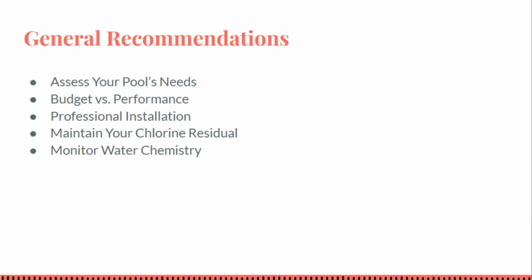Monitor water chemistry. After installation, monitor your pool's free chlorine and combined chlorine levels. You should see a drop in chlorine consumption and consistently low combined chlorine, often 0 parts per million. Adjust your chlorinator output or dosing to the new lower demand. Also check that pH and other parameters stay in range. Ozone has minimal impact on pH, but strong oxidation might slightly lower alkalinity over time. With less chemical input, you may find the water balance stays more stable.